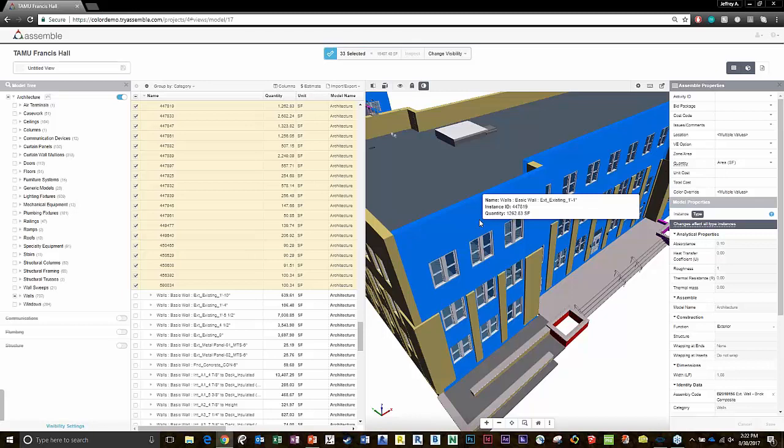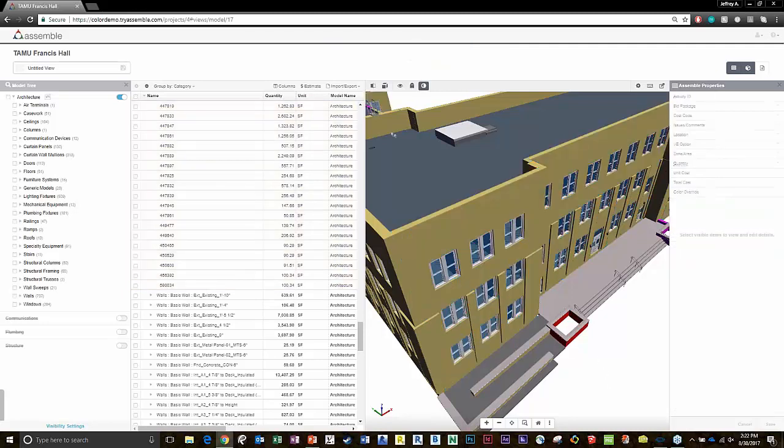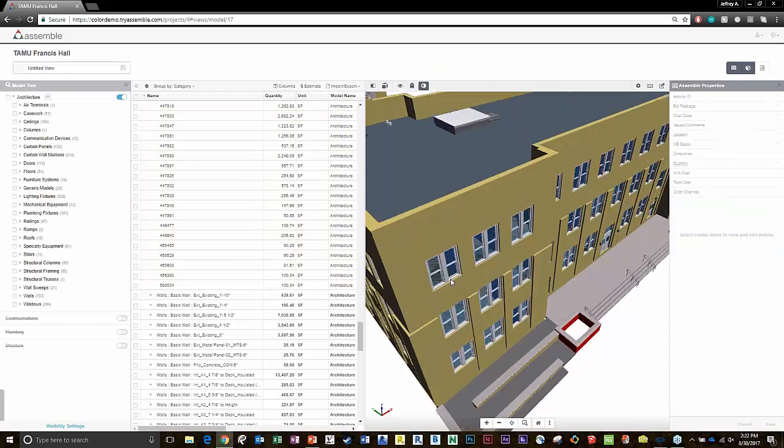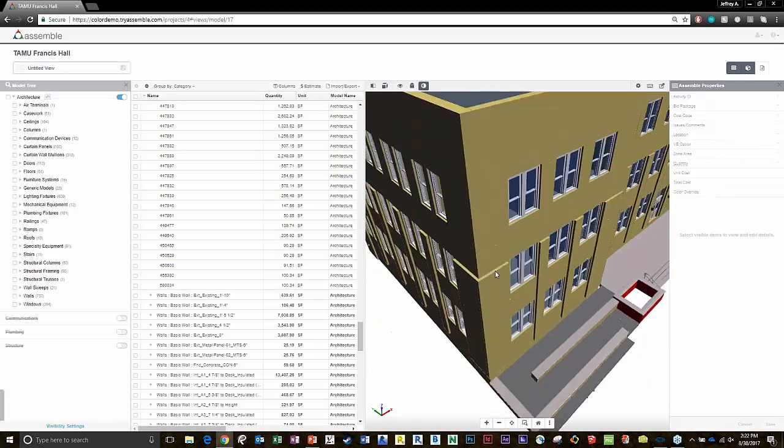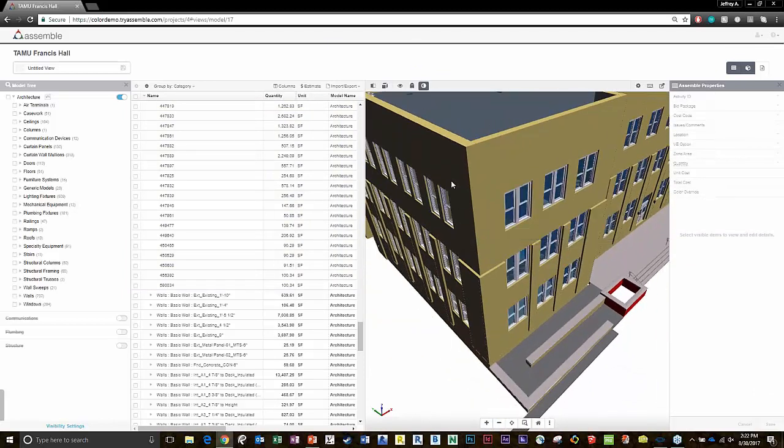The problem with this is if there's a new version of the model, maybe a couple of months or a year from now, and we load that new version and want to do the same takeoff. If we pull open the exterior walls and they added walls, those aren't going to be selected, because it's instance-based, element-based, and not rule-based. Whereas if we do rule-based and they add exterior walls, those are going to be counted in the new takeoff.